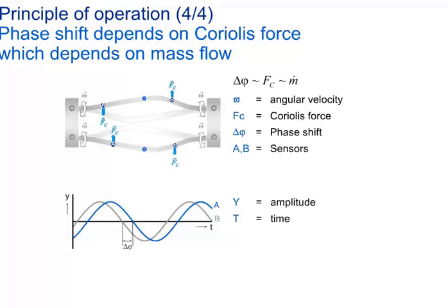However, by applying 2 tubes referencing each other, we can produce much larger differential signals. One tube acts as a reference to the other and therefore does not need any external reference, for example, the tube housing. This makes the meter independent of outside vibrations.